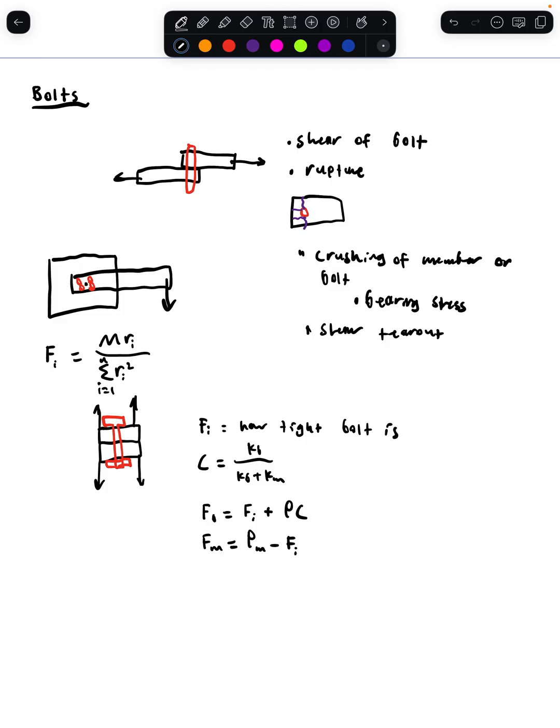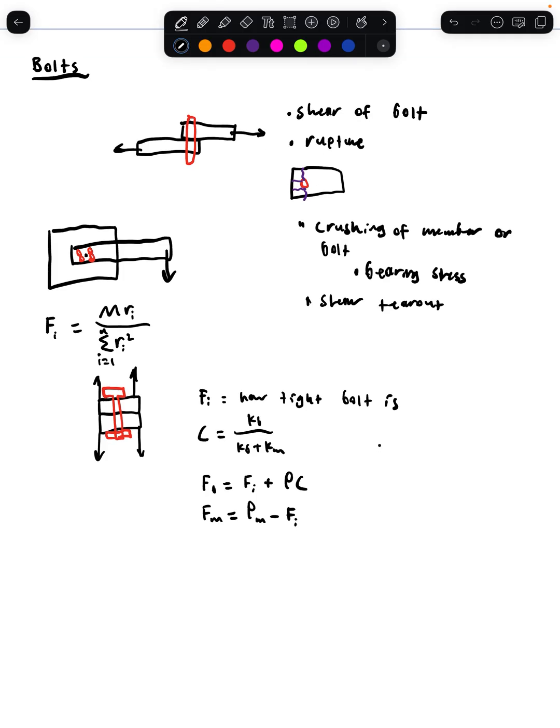One reason you need them is that with bolts, stress is not force over area, but force over the tensile area. This tensile area is not something you can solve just using the radius or diameter of the bolt. They account for it being weaker at the threads, so they reduce the area a little bit.